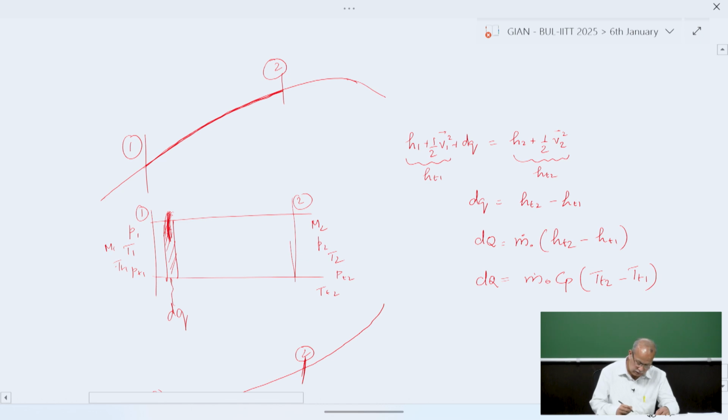So what is dq itself? This is the heat flux. So if you're considering the whole thing, this dq is nothing but the mass of fuel that is injected into the combustor. That fuel will have a calorific value QR. Sometimes it's also the heat of reaction, and in some combustors, not all the fuel will be efficiently converted. There will be a combustor efficiency accounting for it. So this is what we see here.